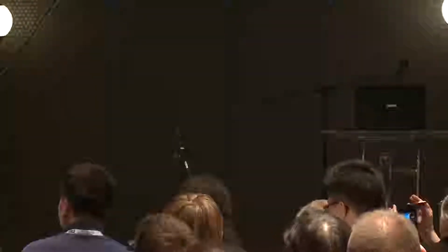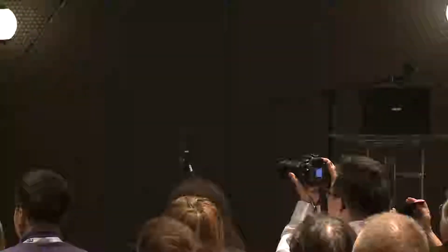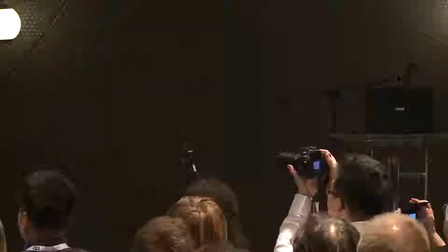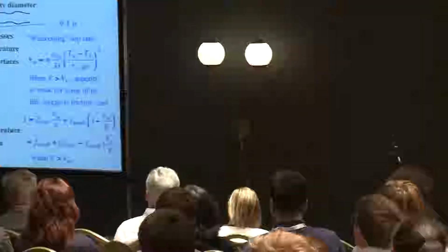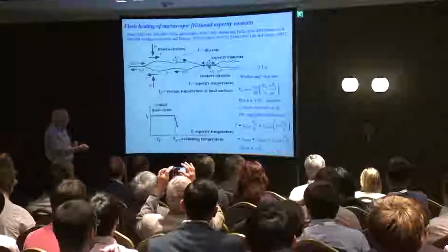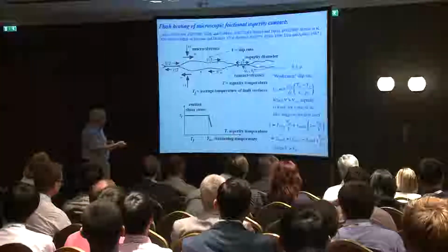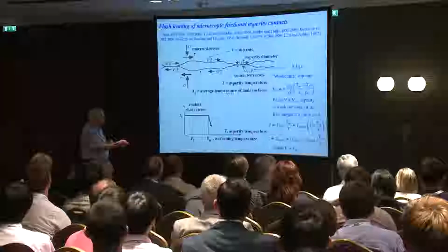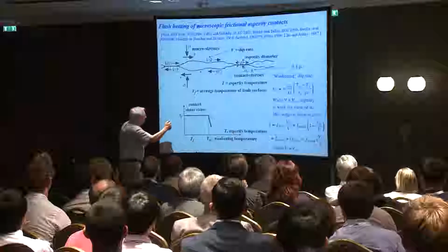Okay, so that weakening temperature could be due to the onset of melting. There are other things that might happen as far as just temperature dependence of the dislocation plasticity in the rock. But that's the simple model that we devised. And so you could ask the question, using heat transfer theory, a simple calculation, you could figure out if you slip at a certain rate, what would that rate have to be for an asperity of diameter d? D is my asperity diameter up here.